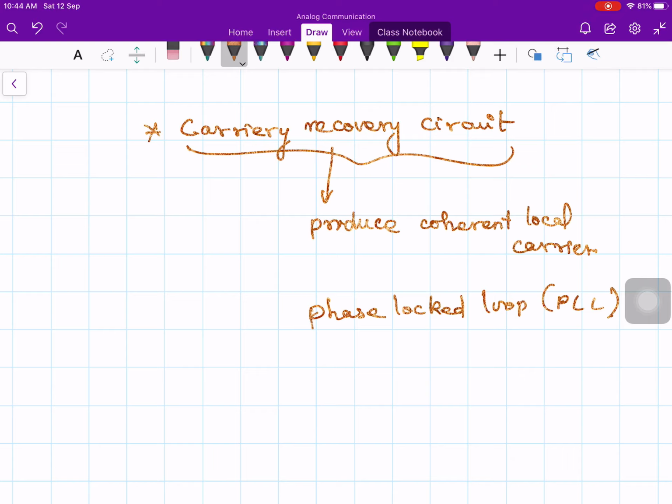In the next lecture we will explore the possibility of a scheme in which we actually transmit the carrier also. If you transmit the carrier also, then there is no need of this phase locked loop, because we already have the carrier, right? With the help of the carrier you can do the demodulation. So let us see in the next lecture whether that helps us to simplify the receiver. In the next lecture we will talk about double sideband AM with carrier.